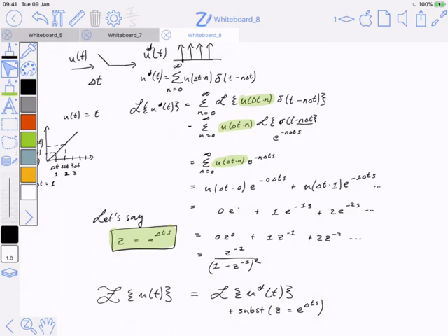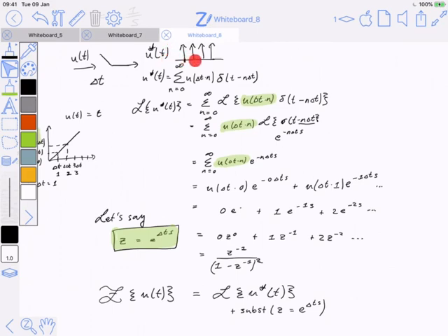So another way of thinking about what the Dirac delta is doing, if you think about a specific delta, it is 0 everywhere except for the time when it's not 0. And that delta has what is called the sifting property. In other words, the only thing that survives being multiplied by a delta like that is the value at that specific moment in time. Everything else gets made 0. And so this is kind of why you can imagine it being like a sampler, right? It's actually just taking out that exact moment in time. It's making everything else 0.